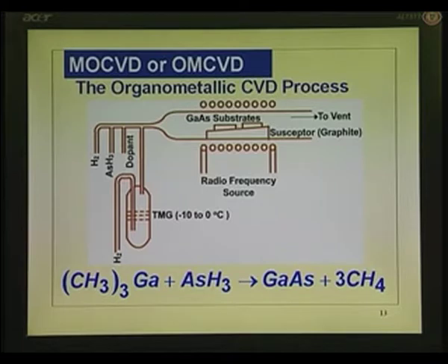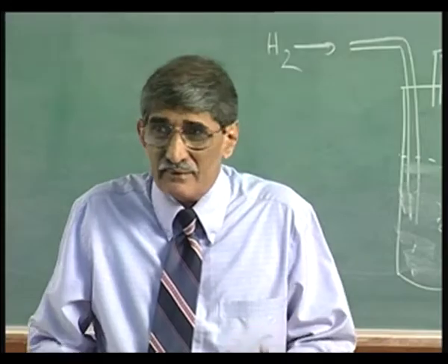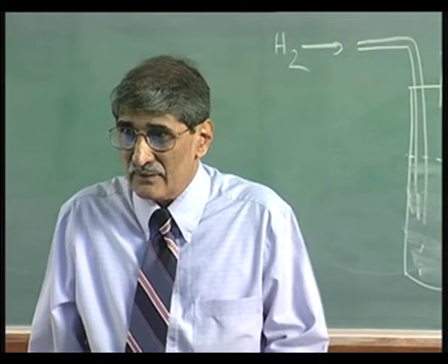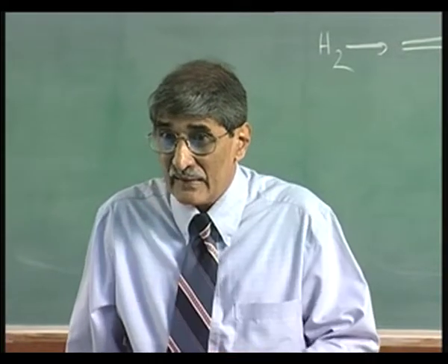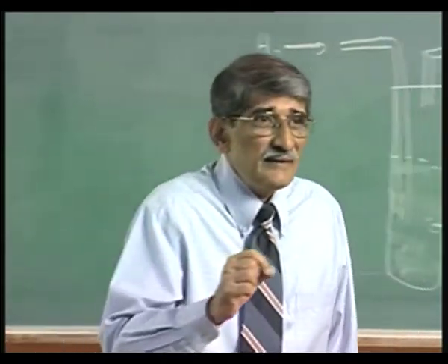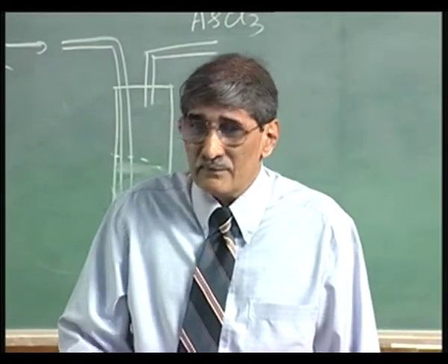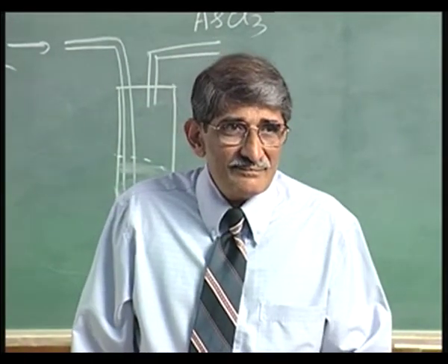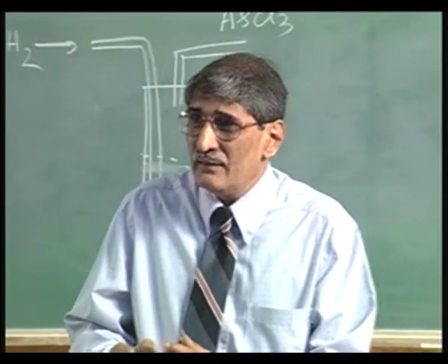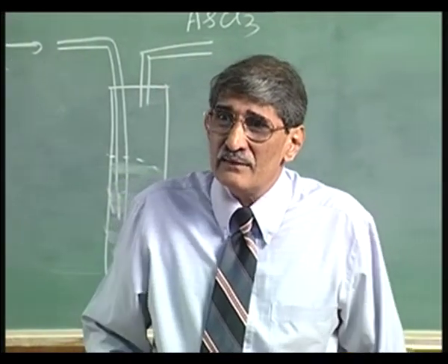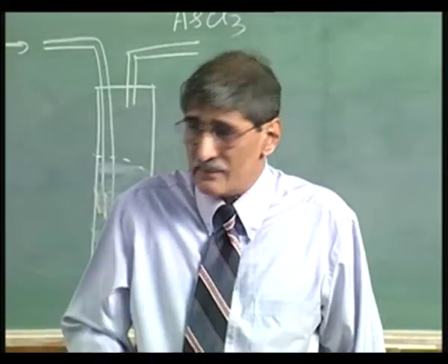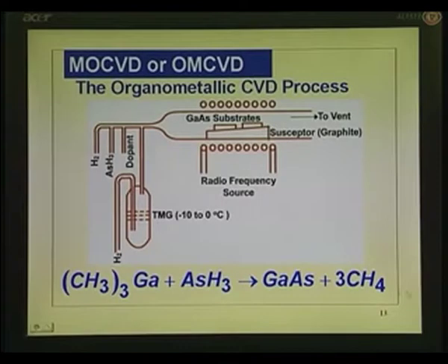People use it, but the general term is MOCVD. So, this is epitaxy. If you use MOCVD on a foreign substrate like molybdenum, you will get polycrystalline material. If you use MOCVD on a single crystal substrate like gallium arsenide, you will get single crystal. So, here it is a similar process, much simpler.